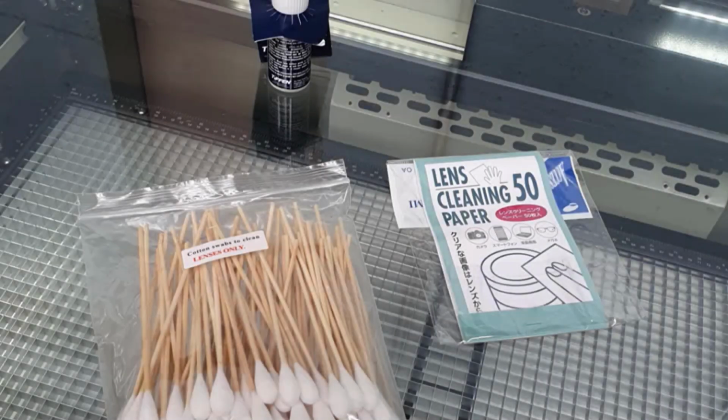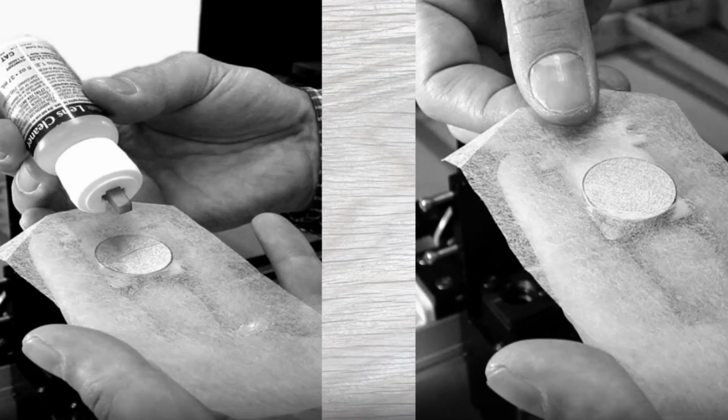Following the manufacturer's guidelines, it's good practice to give the bed and grid a deep clean every academic year as it becomes discoloured due to the laser cutting. Mirrors attract debris, therefore it is important to clean them regularly to avoid permanent burn marks.